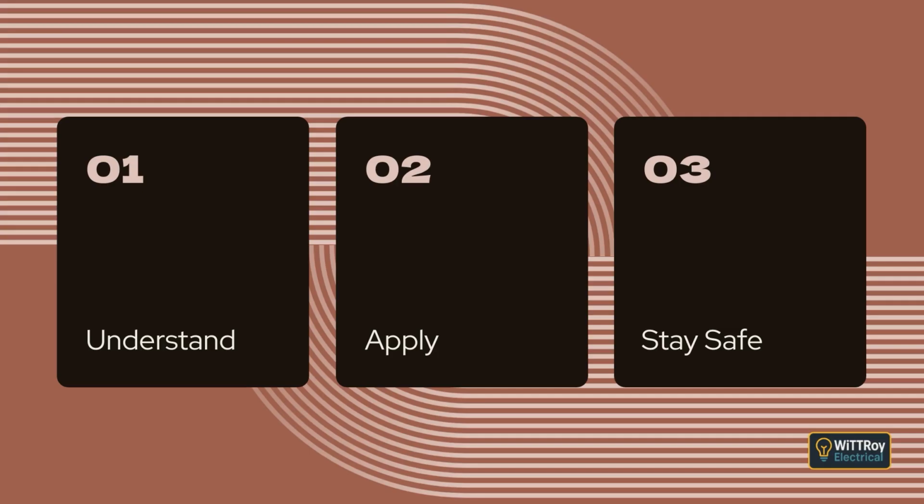When the transformer supplying the premises is dedicated to that installation, the allowable voltage drop may be increased to 7%. For standalone power systems, the combined voltage effects from the source and the installation must not cause the equipment to operate at an unsafe low voltage, and in these cases the total allowable drop may be 11%.